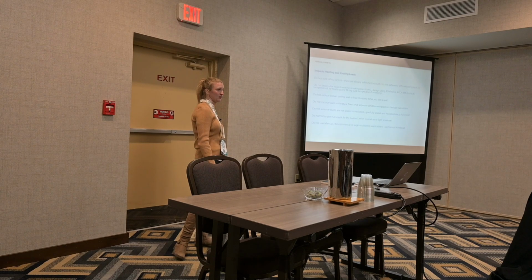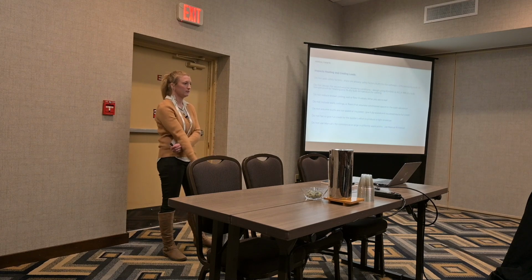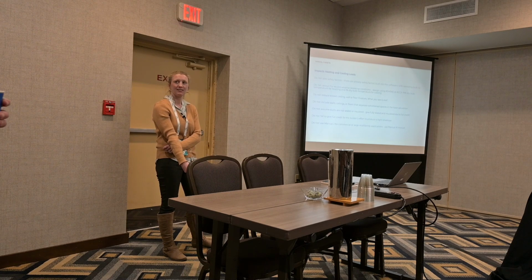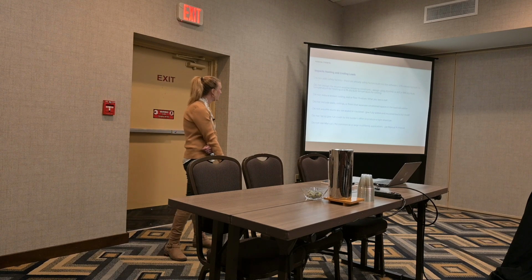I have a question, sorry, back up to number 3 about reducing R values. If you go up in the attic and you see insulation that says R30, but it's installed really badly, that will derate the effectiveness of that R value. Correct. So what you see is real. That would be a reduction from that R30. Right, you're seeing that it is not installed correctly, so you should not put in R30. What you see is real, is the point. If it's messed up, please don't put in the full value.